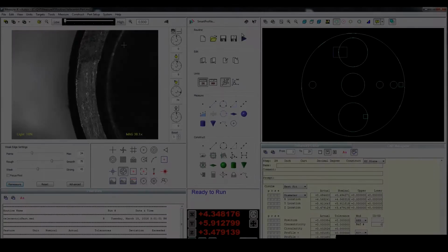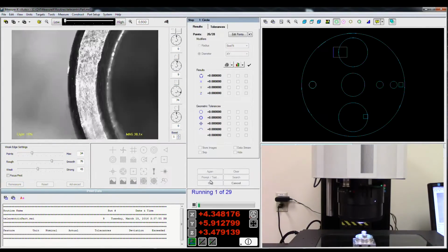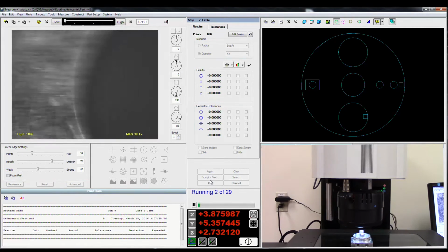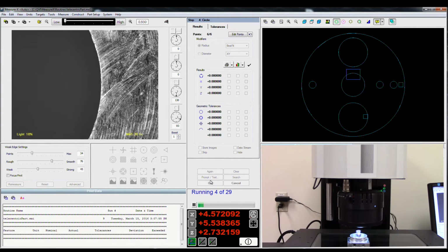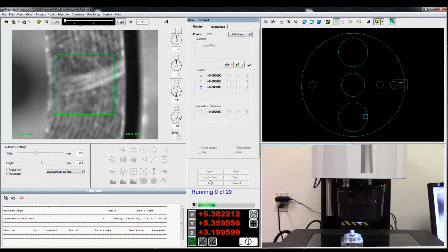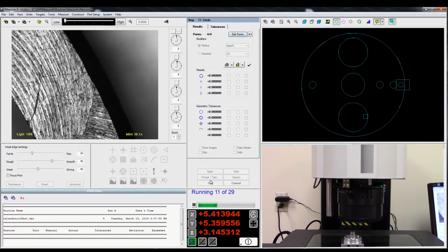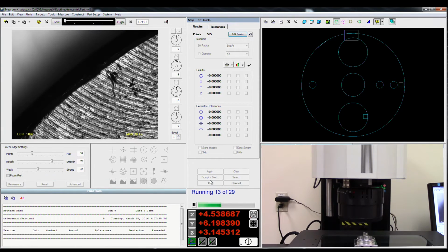The optics or lenses used to magnify the image in traditional video measuring microscopes and comparators have a small depth of focus. The depth of focus is the range of image plane position at which the image may be viewed without appearing out of focus for an object or specimen that does not move or change location during the viewing. This characteristic is very useful.